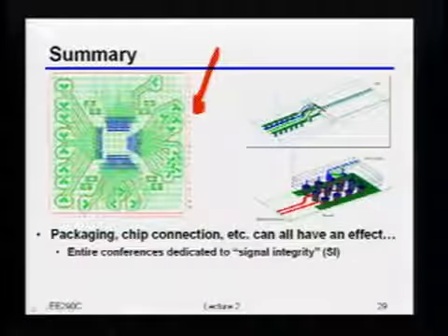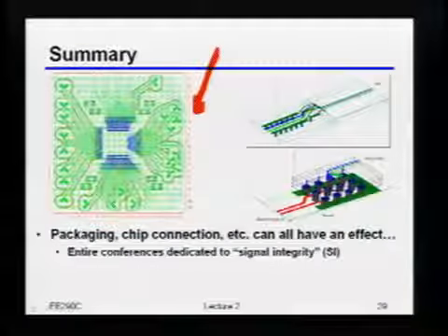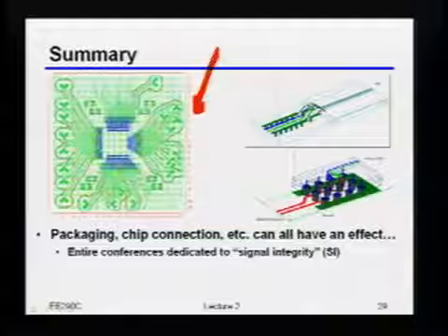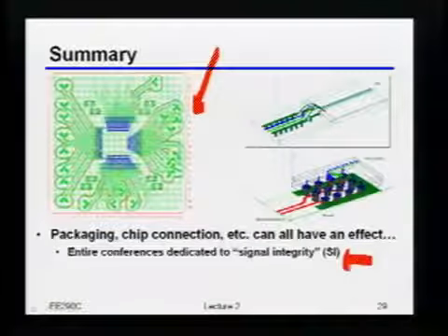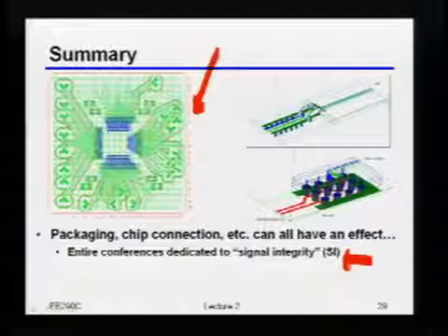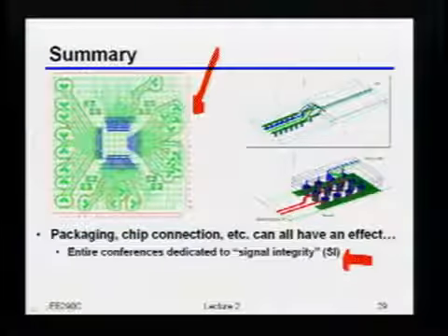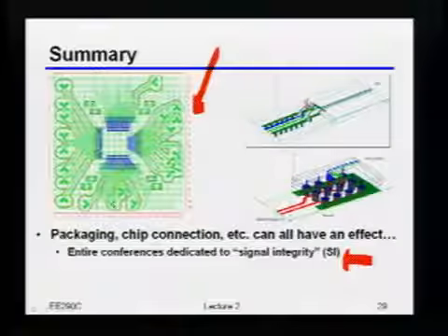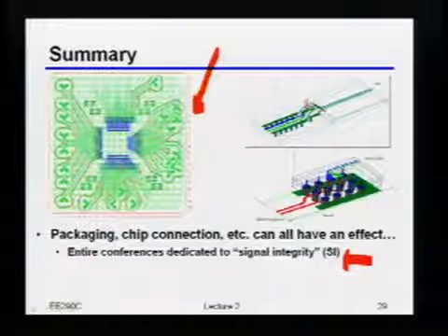So you have to get all those differential signals out, and oh, by the way, they're not supposed to couple to each other, and oh, by the way, you don't want the package to be all that big, right? So in fact, there's a whole subfield of people that really just work on signal integrity, or SI for short. And they'll even do things like plug your chip-to-package transition into HFSS, take the whole package, plug that into some field simulator, and so on and so forth.